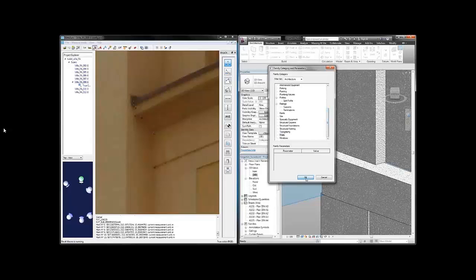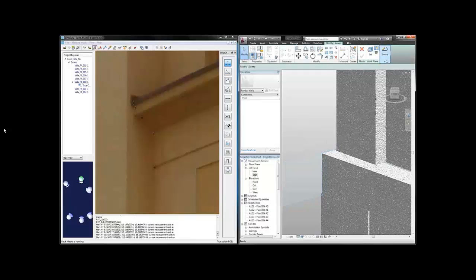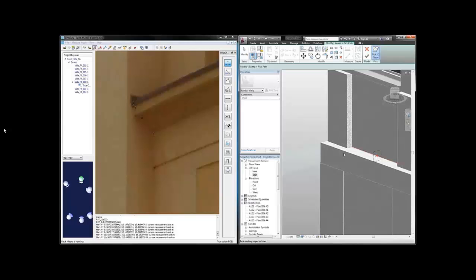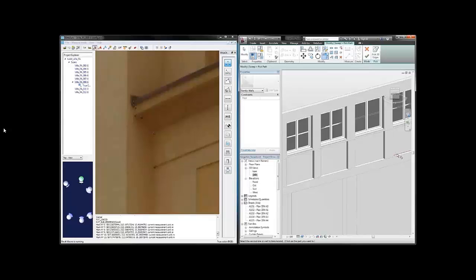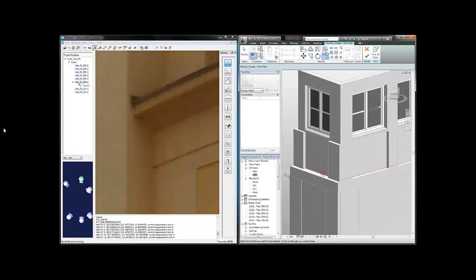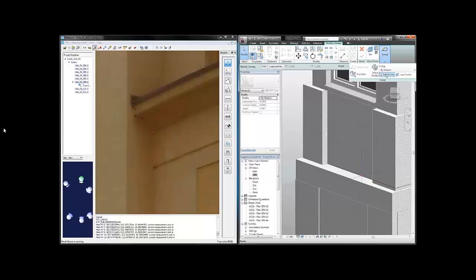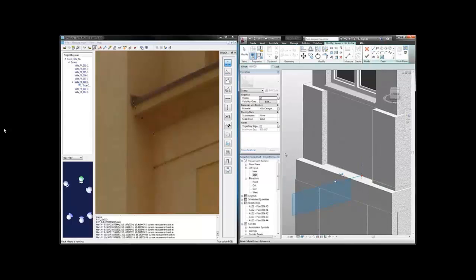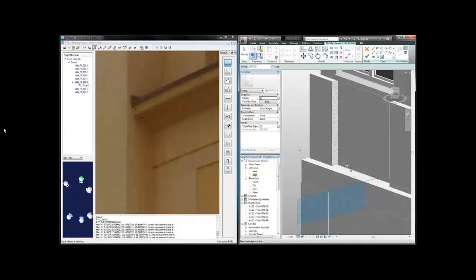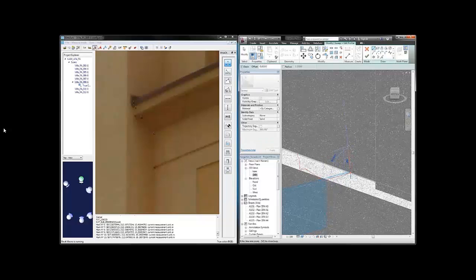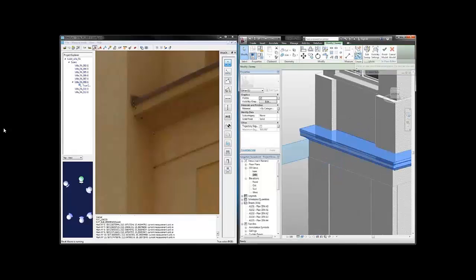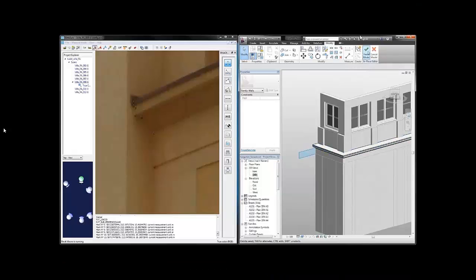We choose an in-place wall family, and using a swept model you can click on existing edges to create the path of your swept. Trim all the lines together, and now you can pick your 3D lines from VirtuSurv to generate the profile for this model in Revit. You have to close this by using all the Revit commands. Trim the lines together, and then it's finished. And with this workflow you can create any other shape you need in Revit.